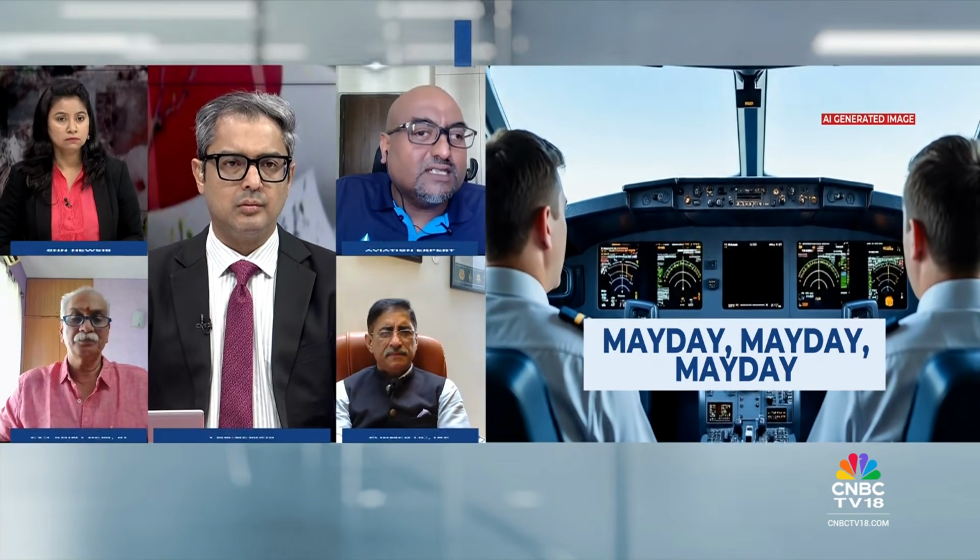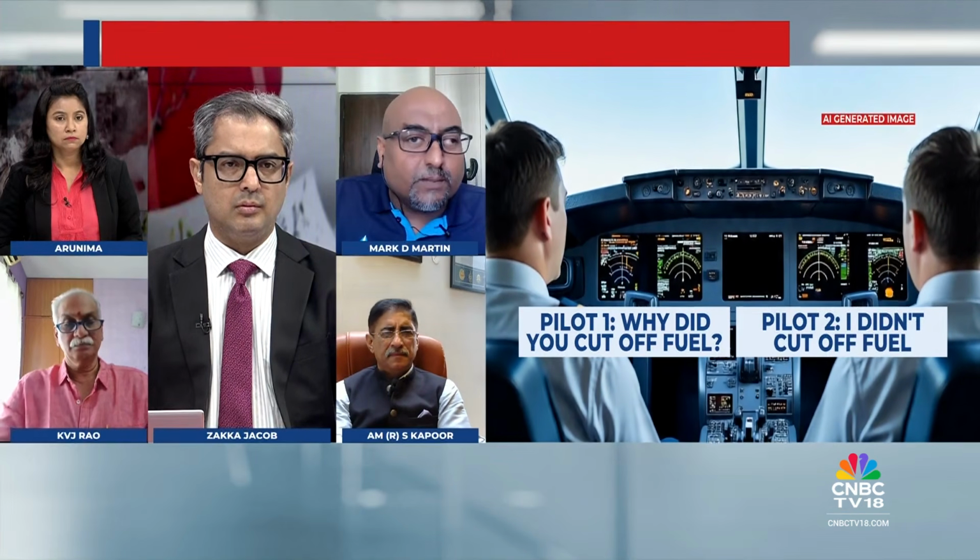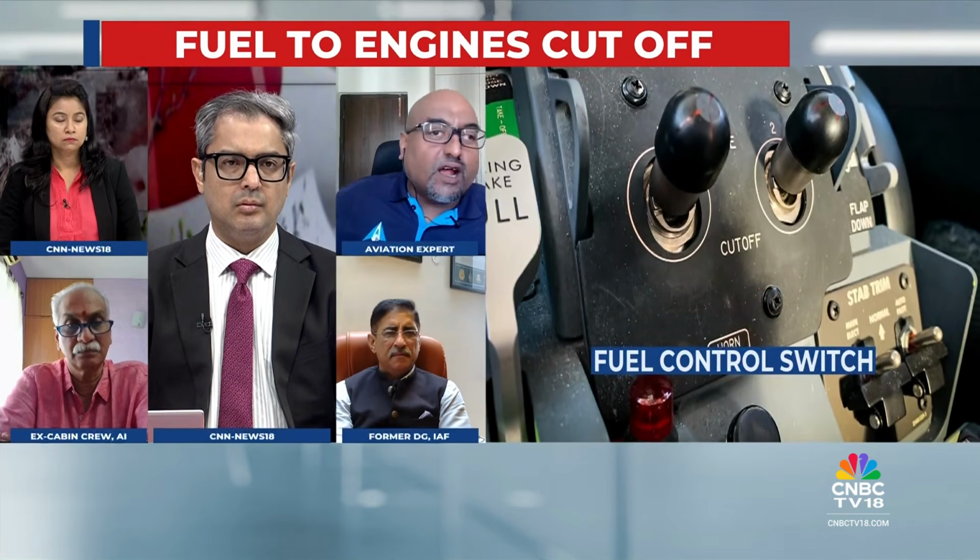seconds to crash. Correct. At 20 seconds to crash, these are micro steps and milestones which have occurred in this incident. The RAT will only deploy when you've lost everything: hydraulics, pneumatics, engine, electrical power, all gone. That's your last resort. You're flying on something called an essential power bus, which, Zaka, is a battery that sits below your seat, and your hydraulic electrical power from the RAT. That's it. Everything has failed. You're down to the last straw.